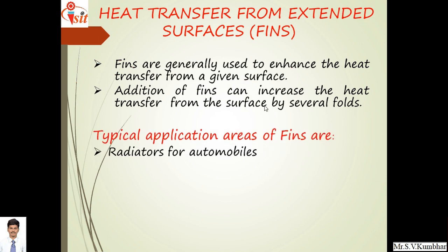Typical applications of fin. First one, a radiator for automobile. Generally in an automobile, the engine is located at the front and here, in order to cool the hot water coming out of the engine, radiators are provided. Radiator is one of the heat exchangers used. If you provide fins to the radiator, then there is enhancement of heat transfer from a given radiator, so water can be cooled in quick time.